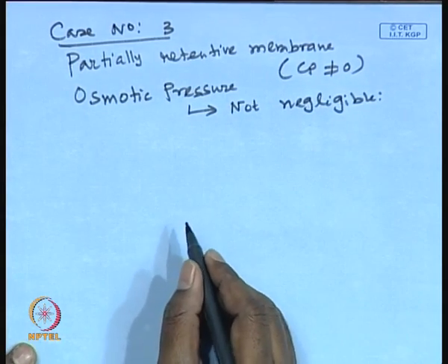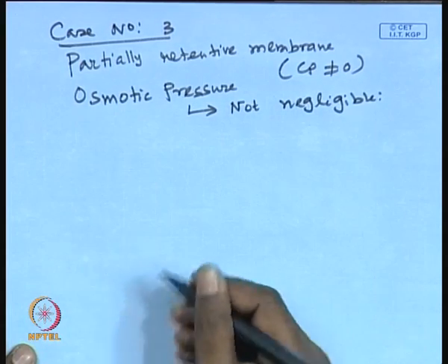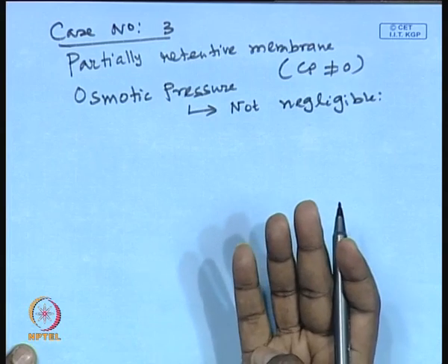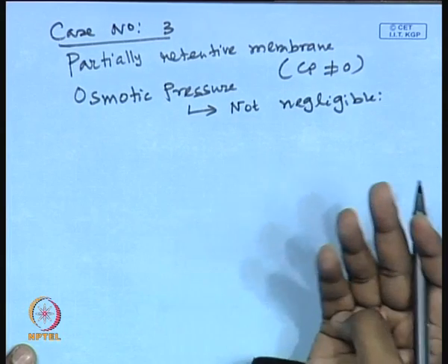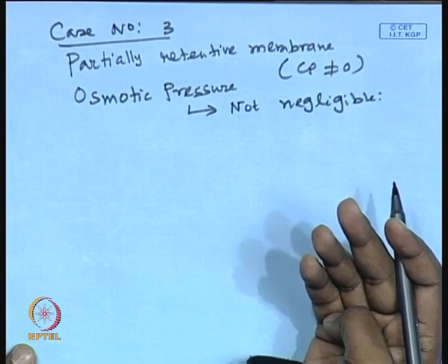Okay. Fine. So, we again do similar types of calculations. We start with the Navier-Stokes equation and hook it up with the velocity, and you will be getting the governing equation of transmembrane pressure drop with respect to x. Then you do the overall material balance, that will give you the governing equation of the velocity, cross flow velocity.